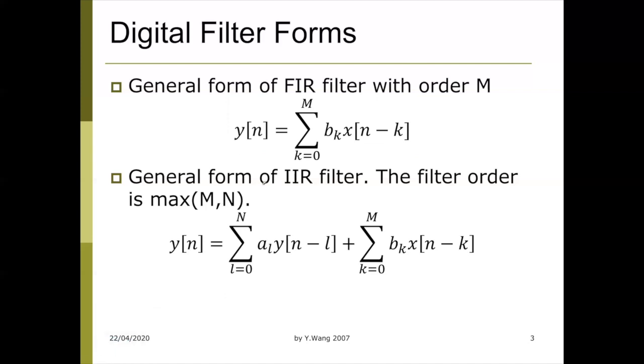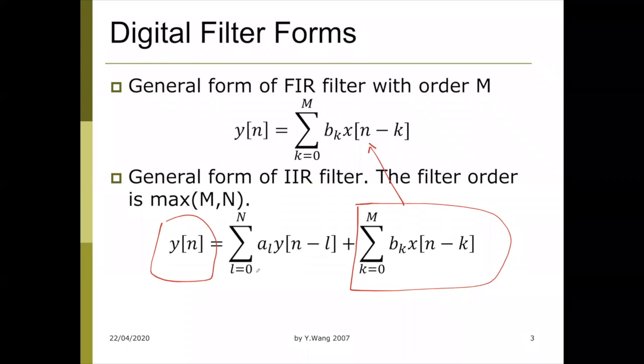However, for the IIR filter, which is the second form, structure-wise, what an IIR filter does is it has a feedback loop within the structure. You still calculate the output signal from the input signal, but there's an advantage of a digital system: you can keep a buffer of the previous output signal. So in that case, your output signal is not only calculated from previous input signals or the current input signal, which is the same as a FIR filter. In addition, it also takes into account the previous output signals. So you basically buffer the output to be used in the future. In that case, it might end up with an infinite loop, because your output signal is going to feed back into the system again and again.